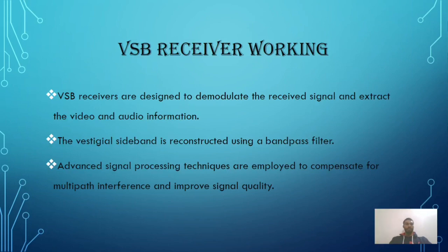VSB receiver working. VSB receivers are designed to demodulate the received signal and extract the video and audio information. The vestigial sideband is reconstructed using the bandpass filter. Advanced signal processing techniques are employed to compensate for multipath interference and improve signal quality.